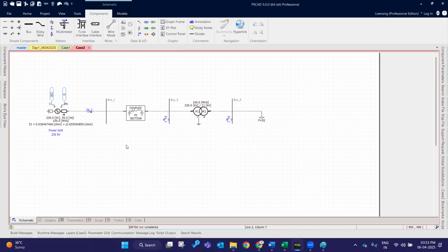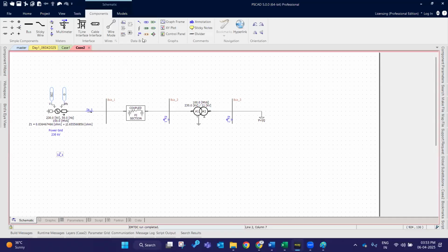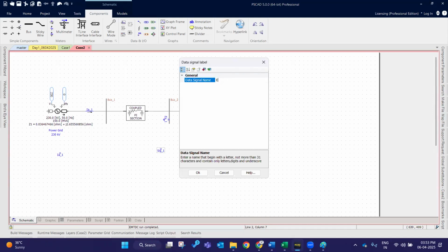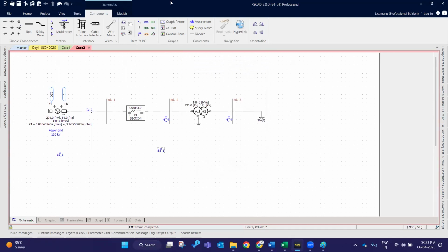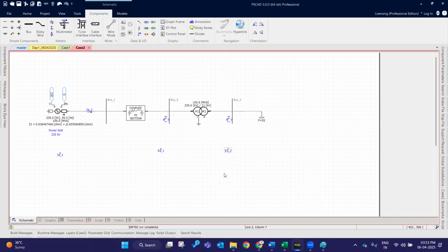So finally, if I'm measuring these three, for example, IA underscore one. First we should define the signal for plotting. Then EA underscore one, then the same EA2. So Control C and Control V. I'm copying the previous signal and just renaming it.